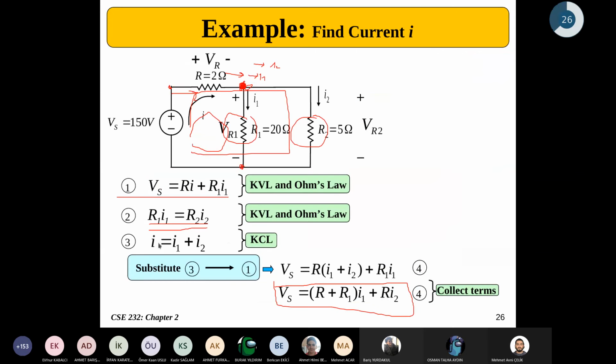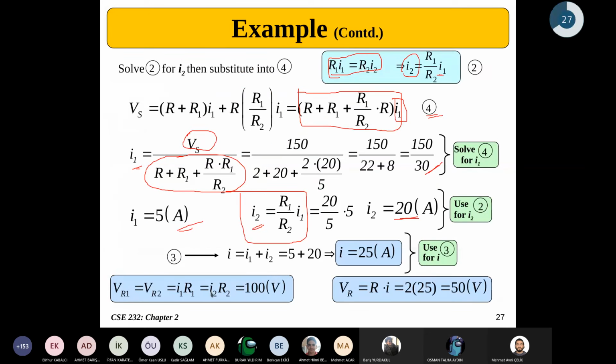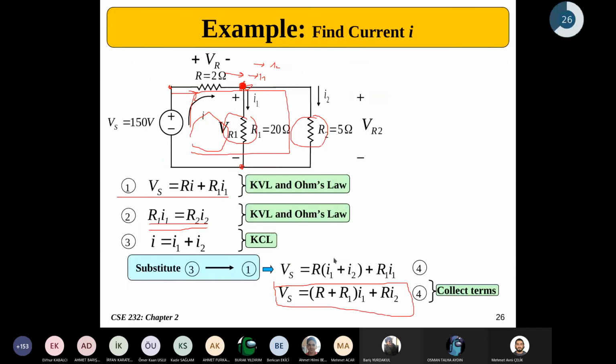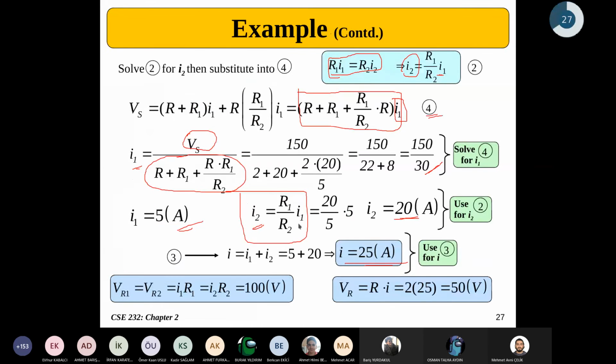And I'll go back and just use the third equation in here to calculate the whole current passing through this first entry in here. It will be just the summation of that too. So from that point, every current passing through every branch in the circuitry is known. So we can do the rest and just calculate whatever we want.